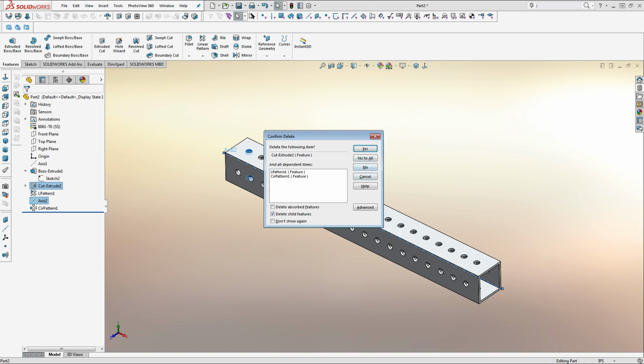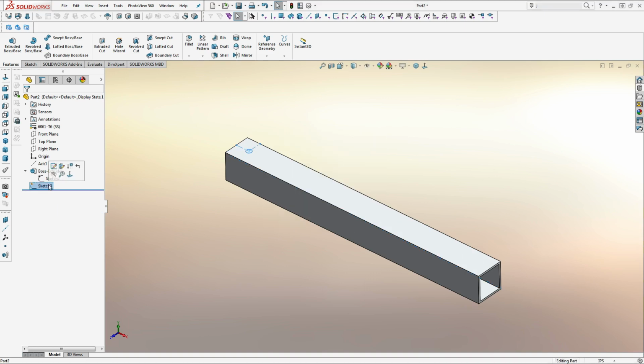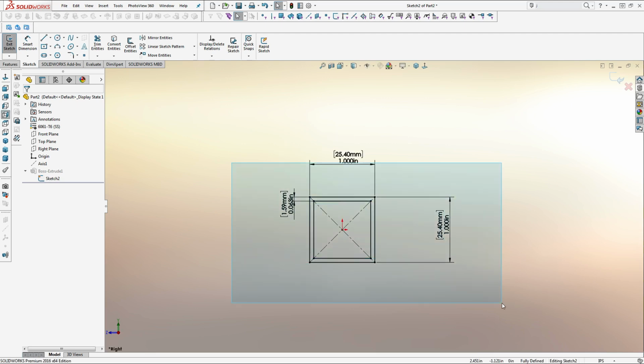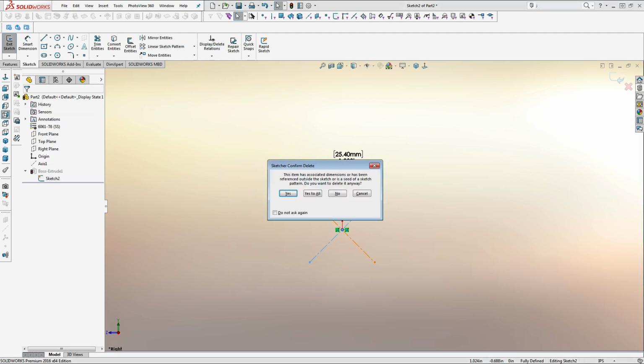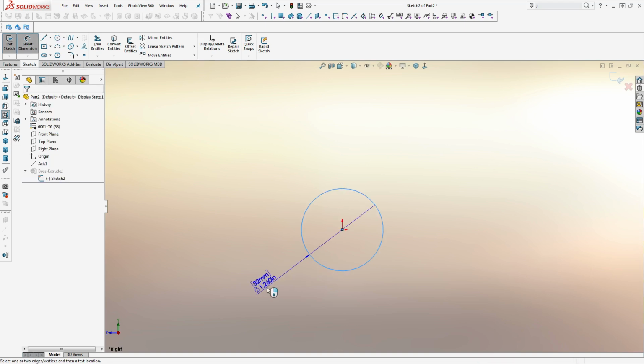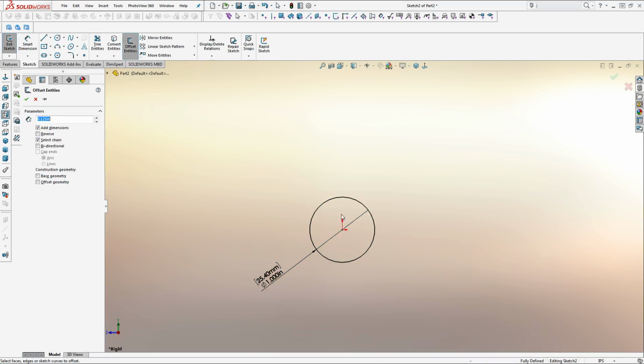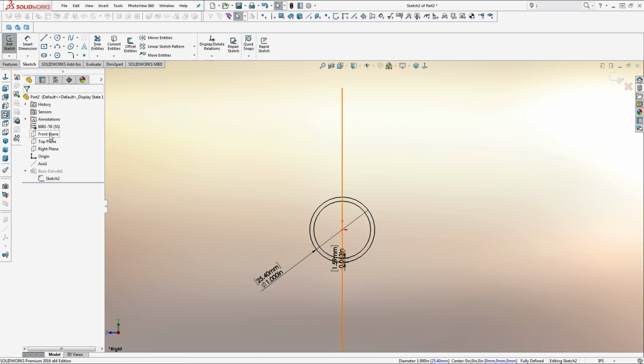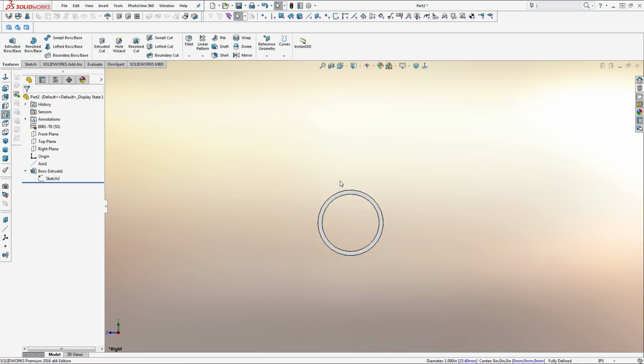You shouldn't be working with anything round yet for the most part. But if you want to do a round tube, pretty much the same procedure. Make a circle, 1 inch round tubing. If I want like 16th wall, offset so it's a 16th on the inside. And it'll do that.